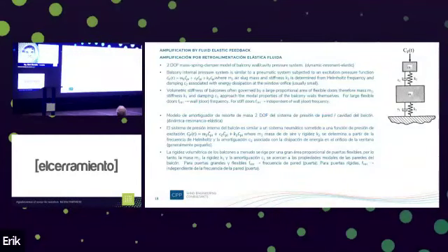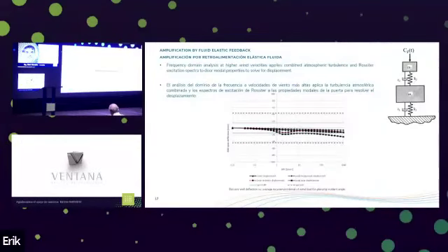Keeping in mind too, as we get to higher wind speeds, the slug of air mass is of limited physical mass to actually excite any further. So these acoustic issues tend to be a problem and annoyance in the serviceability range. But then once we move to higher wind speeds, it's basically the elastic response of the mechanical system.